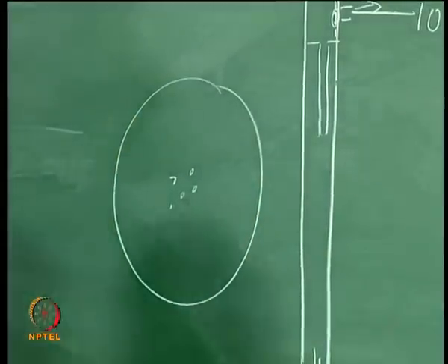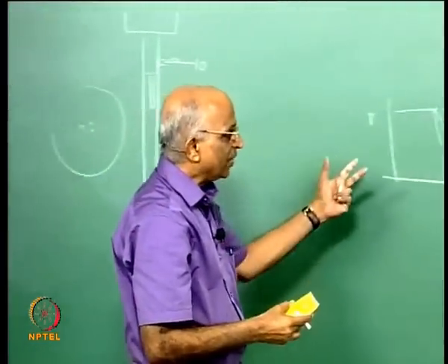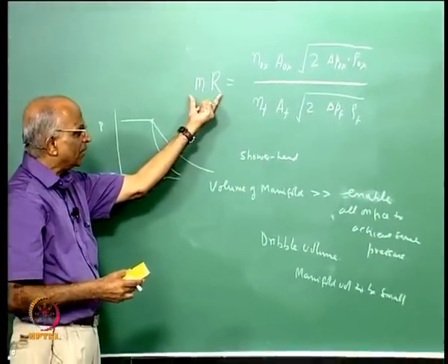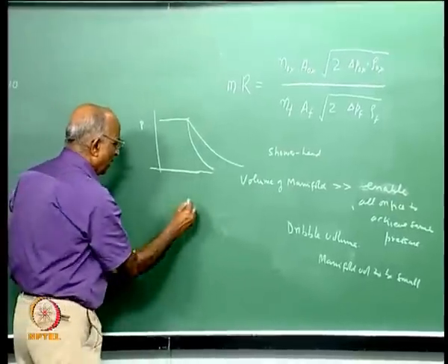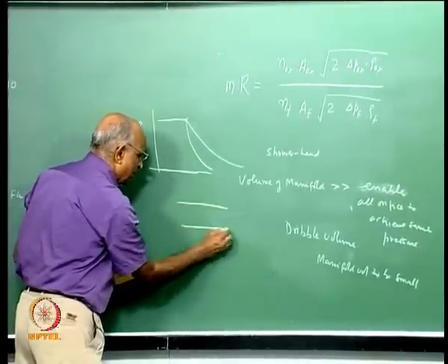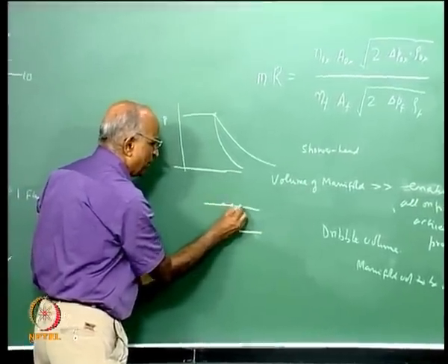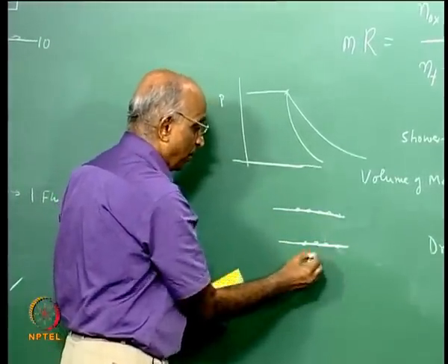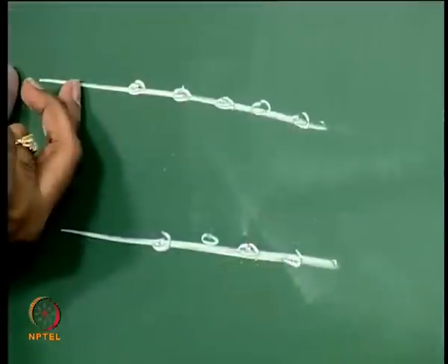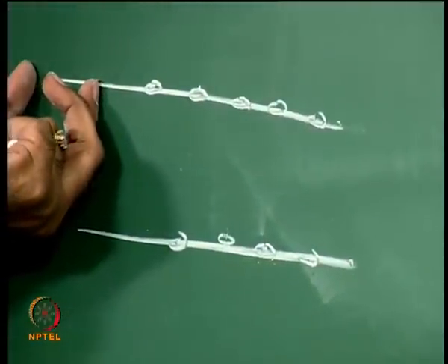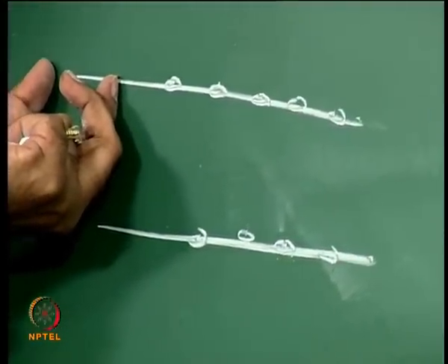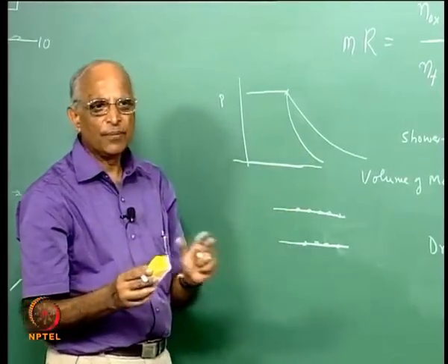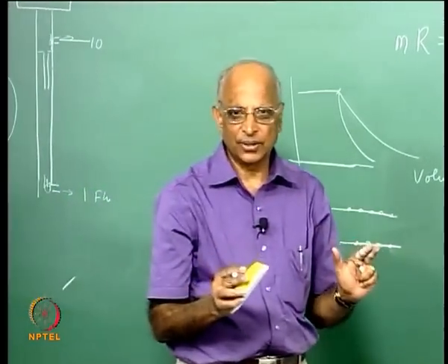These are some common sense things which we use in the design of the shower head injector. But the shower head injector is something like a weak injector, because as you know, if I have a jet coming like this, it takes some definite time for it to atomize and form droplets, but you want droplets as early as possible. Though some of the earlier liquid propellant rockets used shower head injectors, at present we never use the shower head injector.